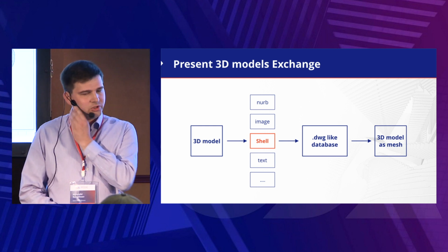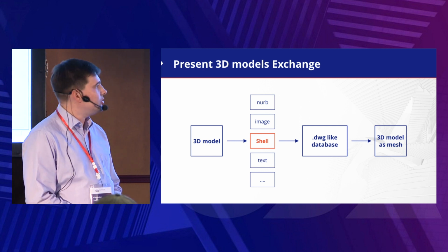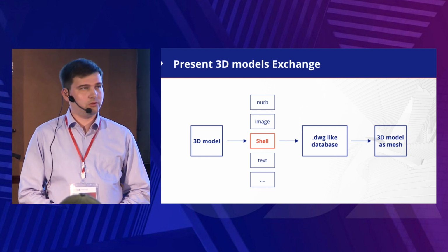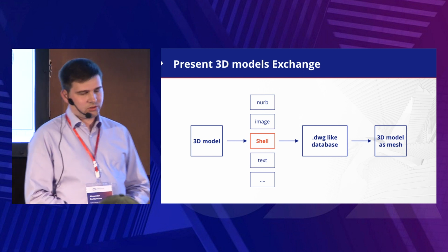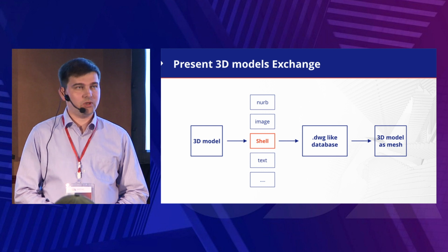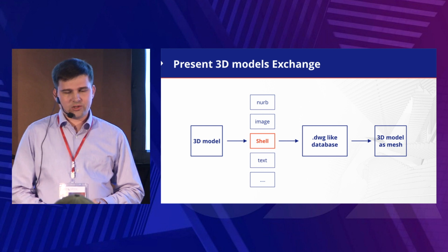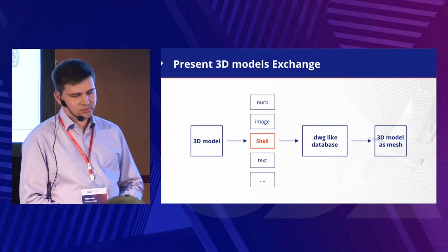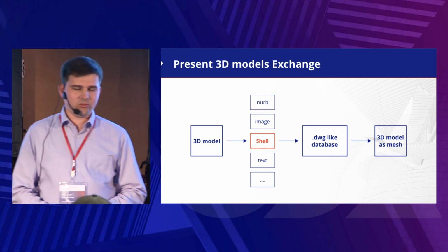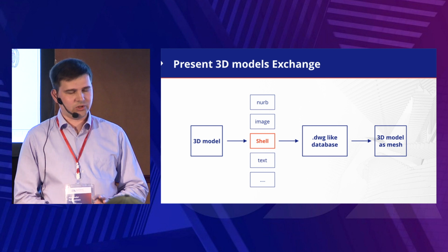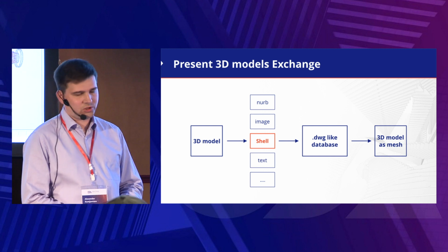So let's go back to the exchange. As I said before, at this moment, Exchange is working via Visualize SDK. At this moment, the 3D model will be tessellated, and Visualize SDK will collect shell data, put it into the DWG-like database, and from this database, this data will be exported as mesh. For DWG format, ODDB polygon mesh or subd mesh entity.